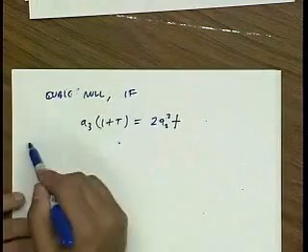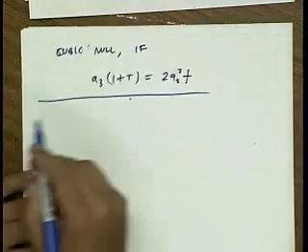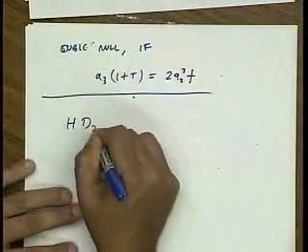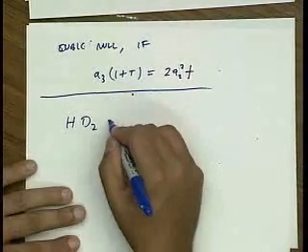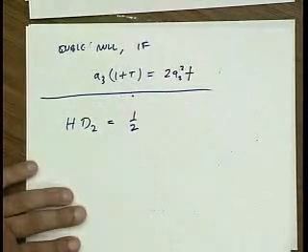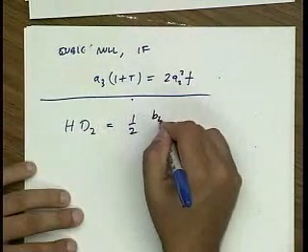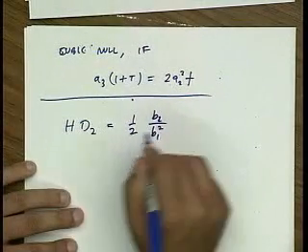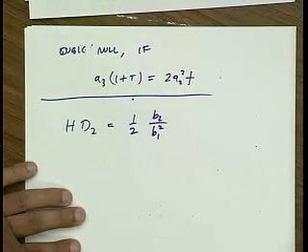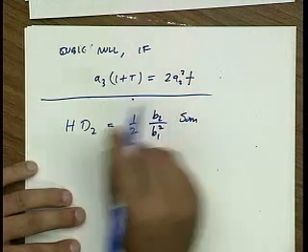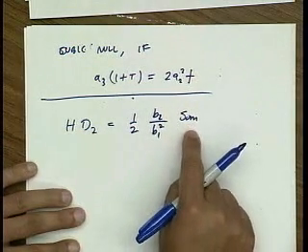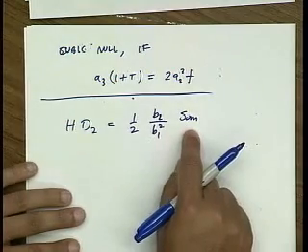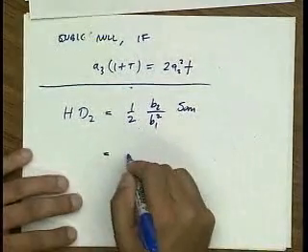All right, so now that we've derived these equations, we can basically go in and plug in the results into all the important metrics. So for instance, if I'm interested in second harmonic distortion, well, the equation I derived a couple of lectures ago, where the second harmonic distortion is related to b2 over b1 squared for a given output signal. It's very important that I compare the same output signal, right? And I'll come back to that in a moment.